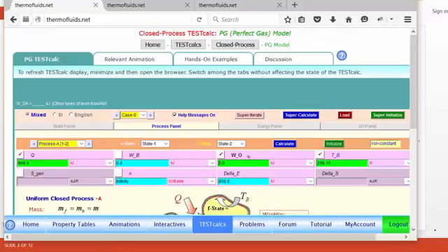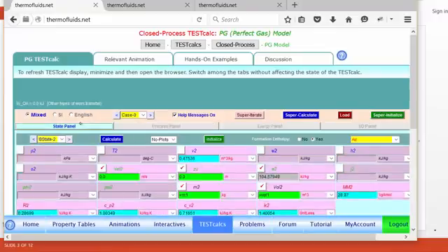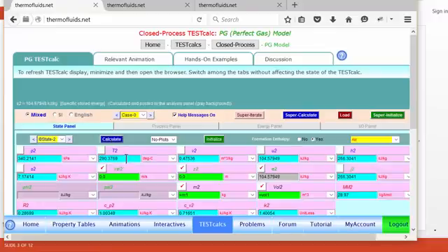Once we enter that and we solve the energy equation, you will notice if you go back to the state panel, E2 has been evaluated and substituted here. That's why it is a gray background. So we can just hit calculate, and therefore the temperature is evaluated.